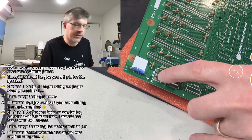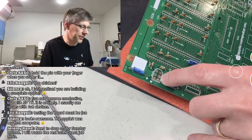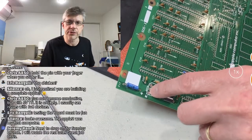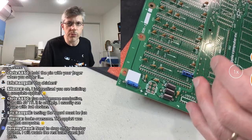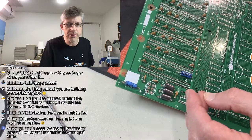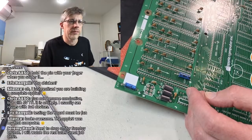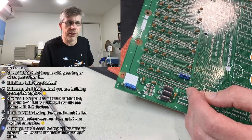So I just tested to make sure like the plus 5 volt wasn't shorted to ground, etc. And then I also went around the board at a few spots and just tested to make sure that, say, the plus 5 volt was indeed hooked up to the plus 5 volt somewhere else. Once you get more and more components on the board, it becomes a little bit dicier to test it. Not dicier in terms of danger, but once things start to get connected together, you can get some false readings sometimes.